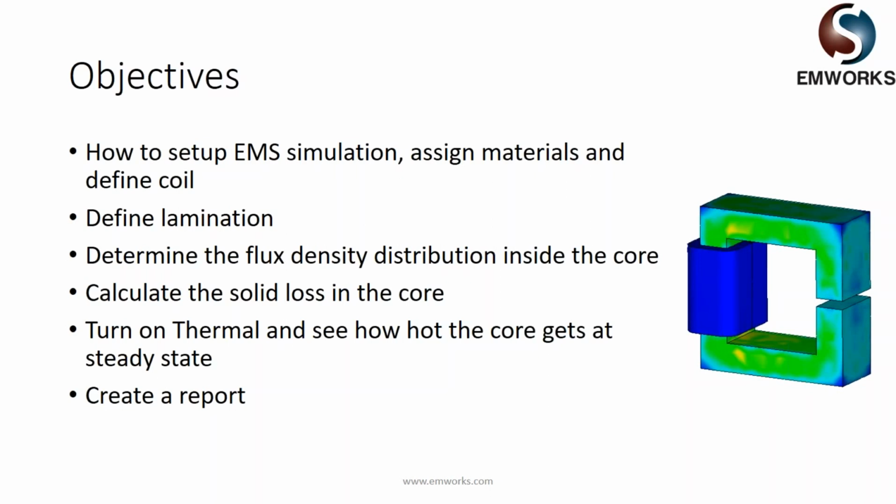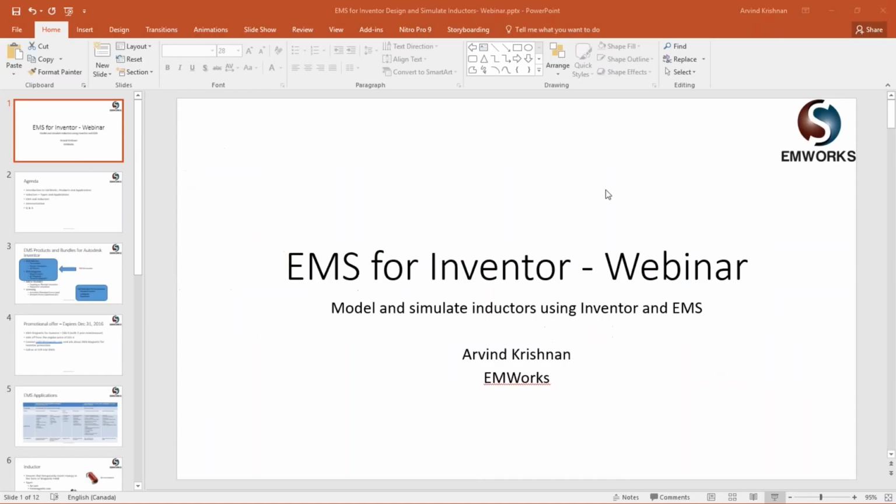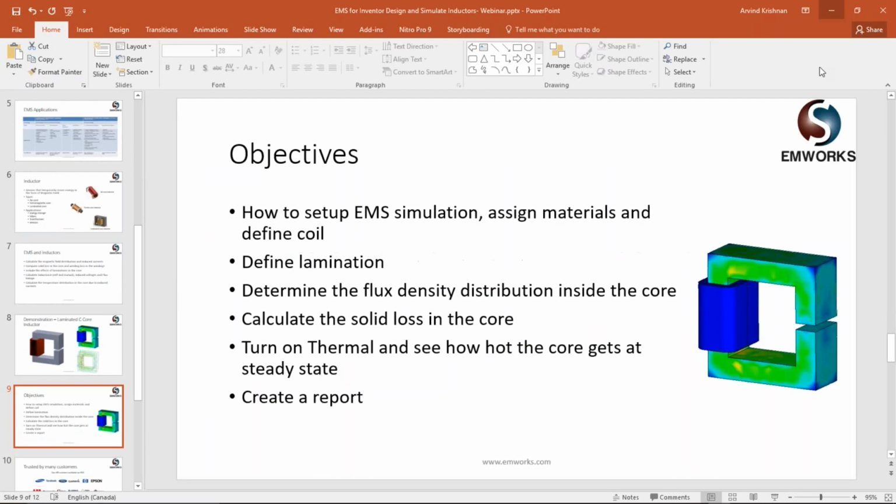Then we will solve, and then we will determine how to study properties like the flux density distribution inside the core, how you compute the solid losses, how you turn on thermal and see how hot the core gets, and so on. And we will see how to create a simple engineering report, a simulation report, right inside the product.